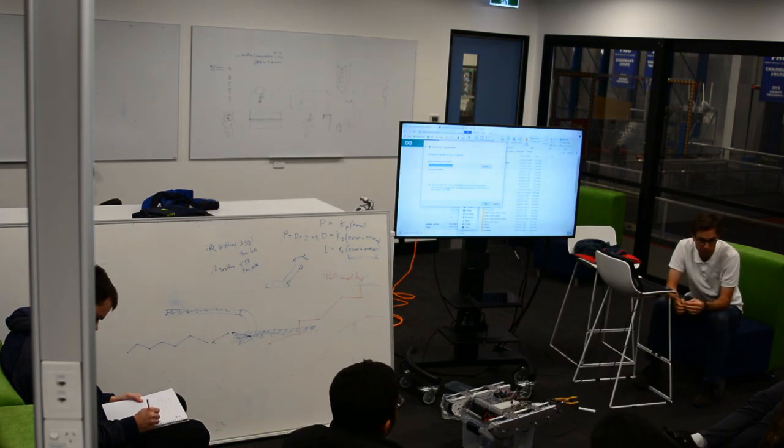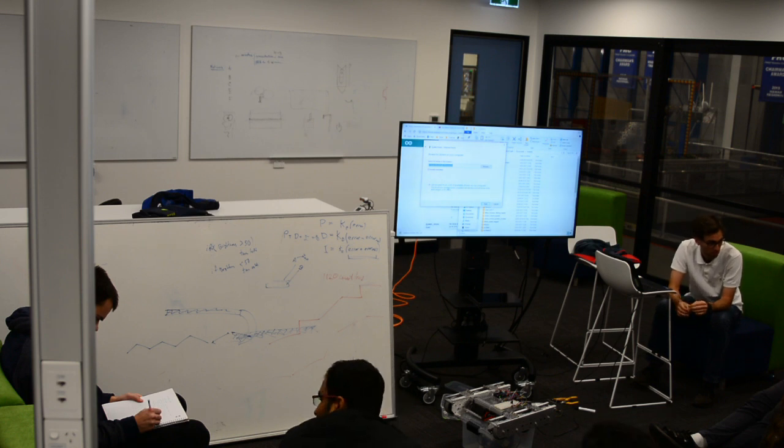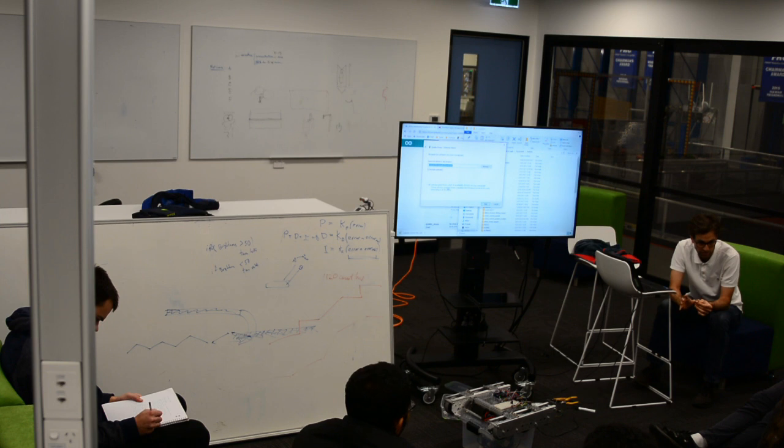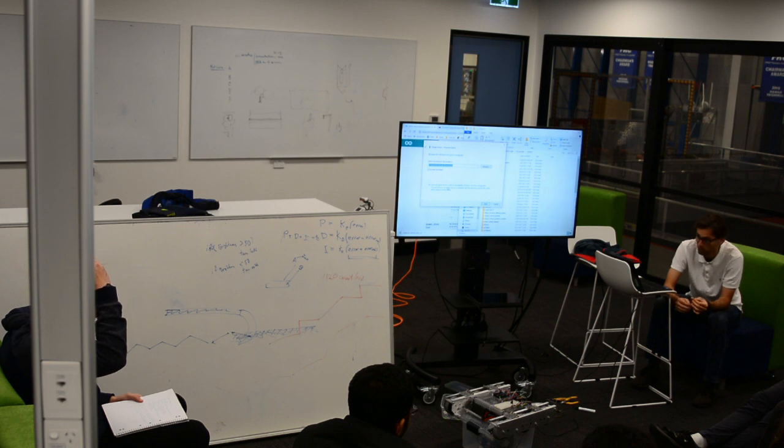And you can spend a lot of time buried in trying to tweak something and get it to work. The fix to that is to have a tight control system that is only meant to make small moves, and that should help fix that problem, whatever it is. But you certainly could get out the PID library and spend an hour or two just tweaking those parameters until it works.